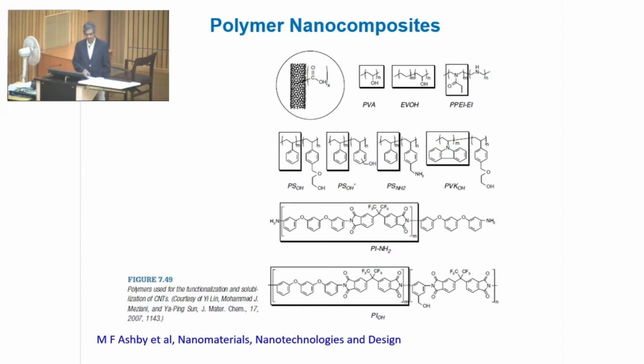So, polystyrene nanocomposites filled with CNTs have been produced, and compared to the pristine sample, the modulus of aligned composites increases almost by 50%. So, that is something which is widely used for many purposes. In addition, aligned CNT polystyrene nanocomposites were also shown to exhibit increased yield strength and ultimate tensile strength, UTS, compared to the pristine ones, due to the fact that CNTs exhibit high electrical conduction.